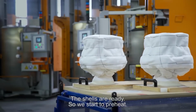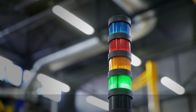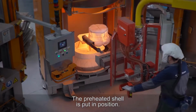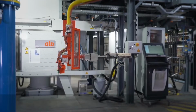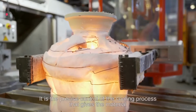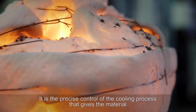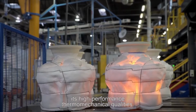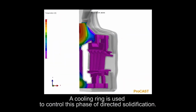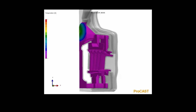The shells are ready, so we start to preheat. The metal is loaded and brought to the melting point. The preheated shell is put in position. Casting completed. The cooling stage is crucial. It's the precise control of the cooling process that gives the material its high-performance thermomechanical qualities. A cooling ring is used to control this phase of directed solidification.